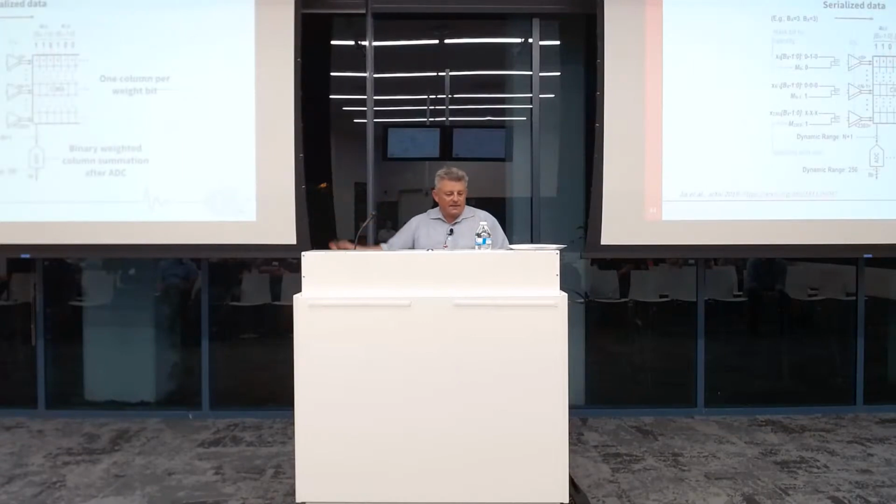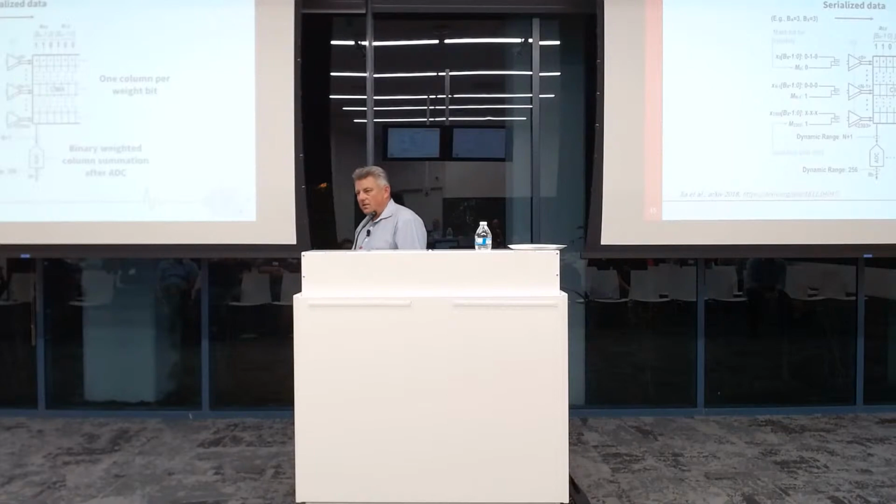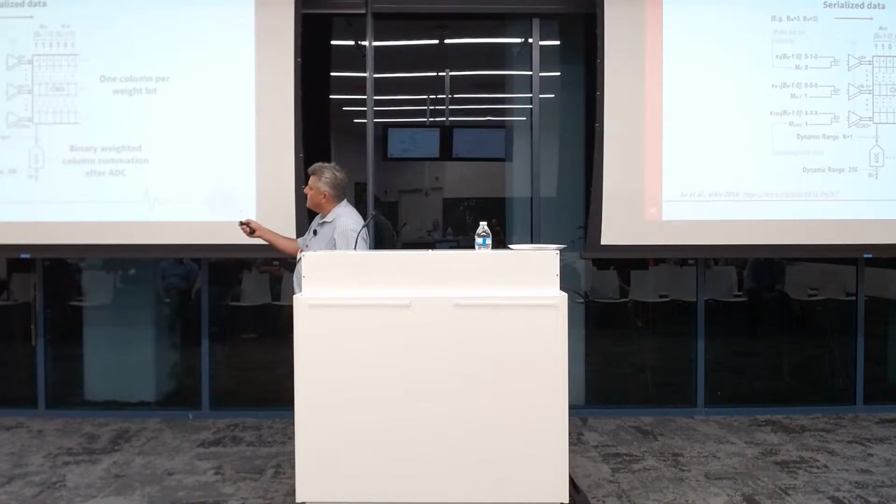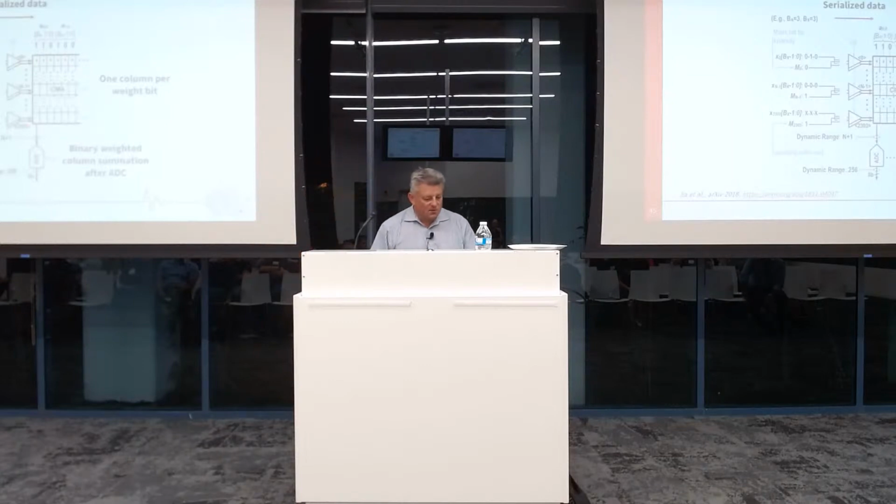So, you know, Naveen and his gang have been working on this for a while. They can also do multi-bit with this. This concept is not limited to single bit. You can actually distribute weights in multiple columns. You can shift your input data across these weights and then just accumulate in the columns. So there's a way to extend this to multi-bit.